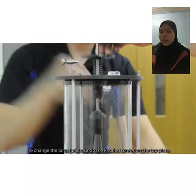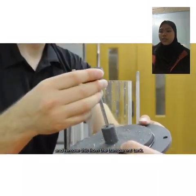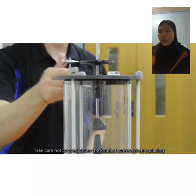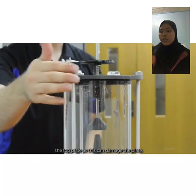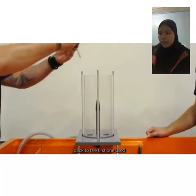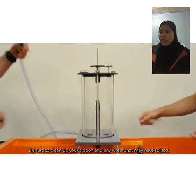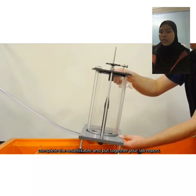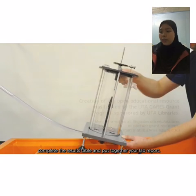To change the target plate, undo the knurled screw on the top plate and remove it from the transparent tank. Take care not to over-tighten the knurled screw when replacing the top plate, as this can damage the plate. When finished taking readings, replace the deflector back to the first one used. Be sure to clean up your station and any water that may have spilled. Complete the result table and put it together in your lab report.